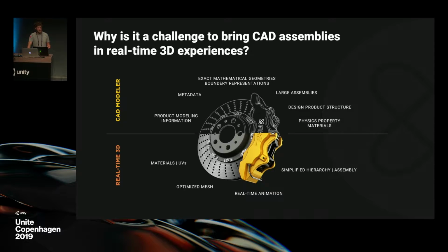And finally, it's common that a CAD model doesn't contain visualization information like proper materials, shading information, and UVs. So now, how do you go from a CAD file like an Autodesk file to meshes actually usable in Unity? Well, that's when you use the PiXYZ solution. With the process that we're going to show, we start with the first step, which is file import.